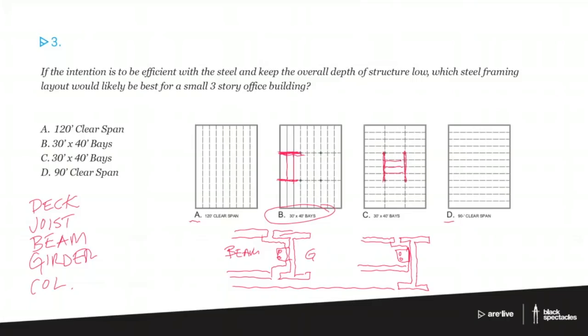So just as a quick reminder, if you think of, let's say, a W21 by 40 or something, I'm making that up. I'm not even sure if that's a real size, but it's roughly similar to a real size. That would be a wide flange. That's what the W means. And then the 21 is the nominal depth, so 21 inches tall, roughly. And then the 40 would be pounds per linear foot.